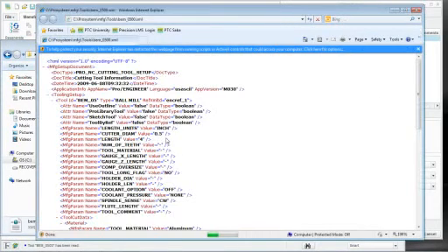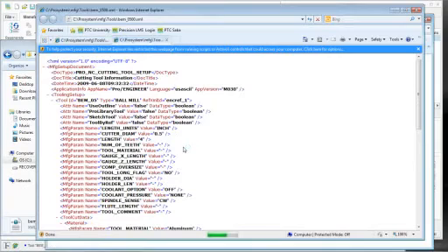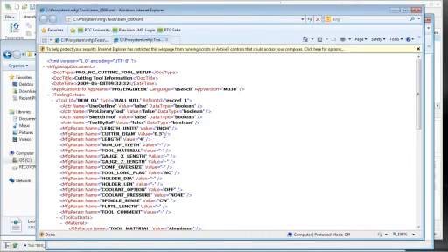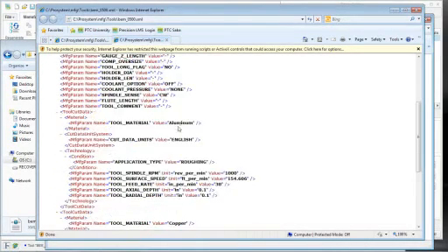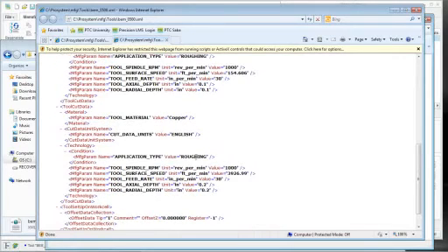All right, so what you see in the .xml file is general information. You talk about the length, the cutter diameter, but what you see here is the tool material, what the application is, and the information for speed, feed, and depth of cut. And then a little bit lower is copper, the application, and the values for speed and feed. And again, as I save that, all it does is continue to append this .xml file. All that information is stored in that spot, and from that point it is pushed, or can be pushed, into your parameters.